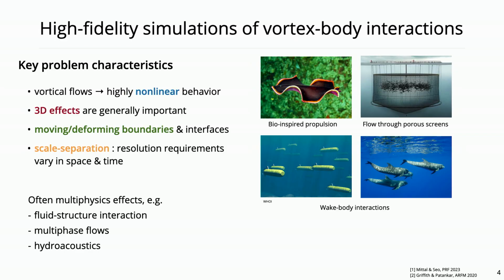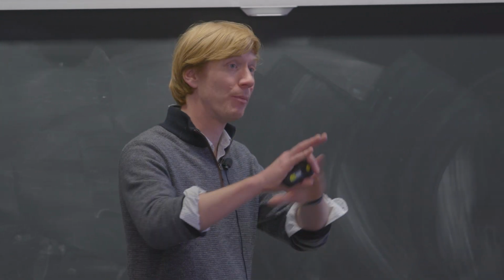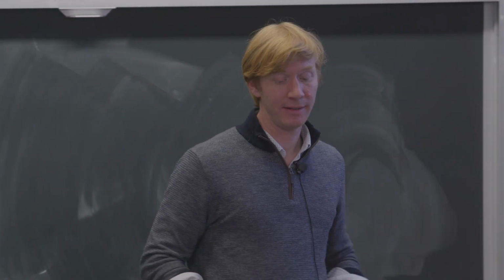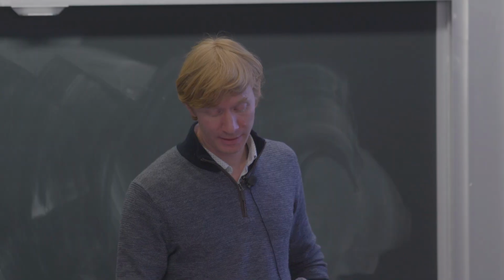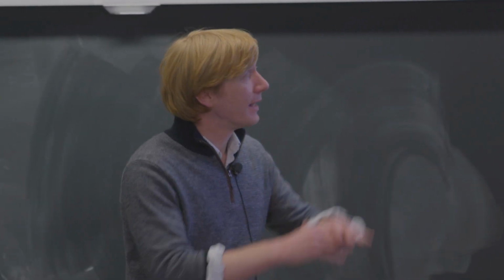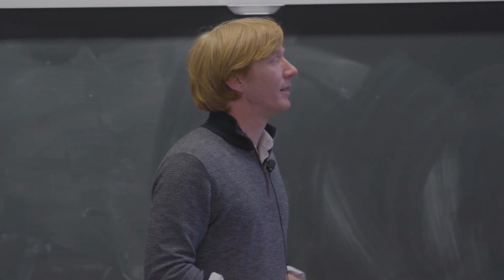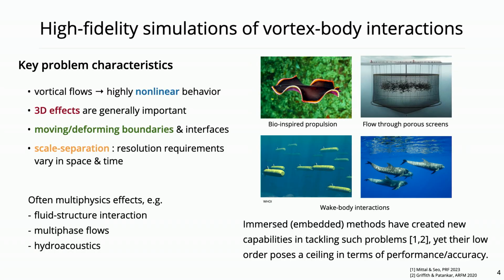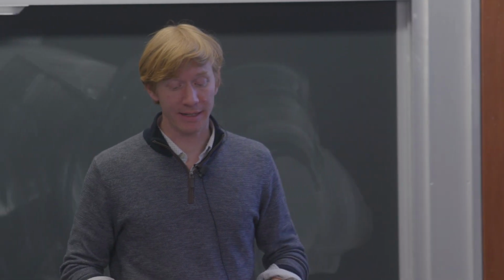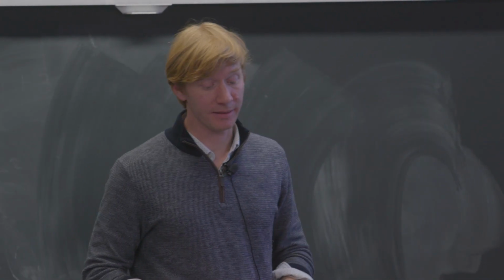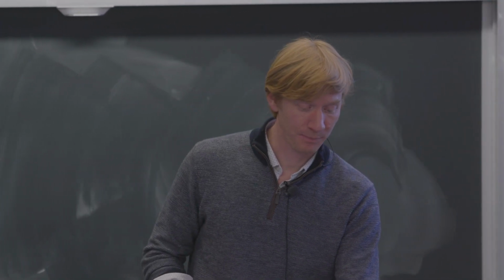And then there's also often multi-physics problems. So we want to think about fluid structure interaction, multi-phase flows, hydroacoustic things that couple different physics across different domains. And so we want to think about those things when we develop our method as well. So within this broad category of problems, immersed methods have created a lot of new capabilities, and it's a popular method in academia, some also more and more in commercial and sort of practical solvers over the last few decades. But they are typically characterized sort of universally by a low order of accuracy, and I argue that poses a ceiling in terms of what they can achieve in terms of performance and accuracy.